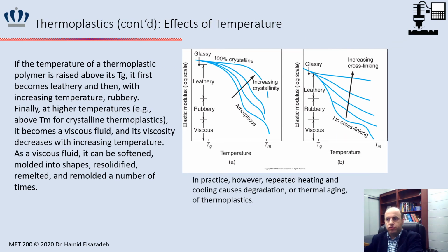This slide shows the effect of temperature on the strength. As you see, with increasing temperature, the strength and the modulus of elasticity decrease, and ductility actually increases.